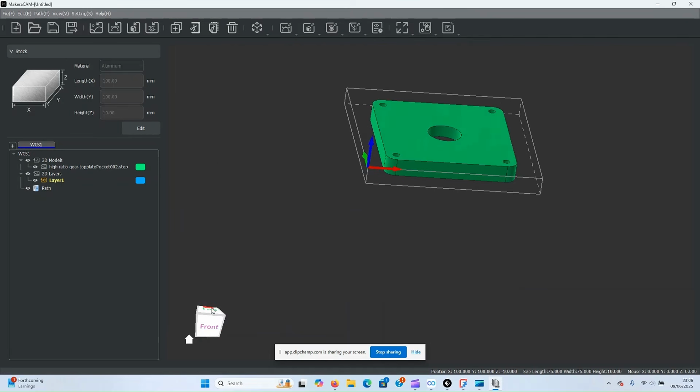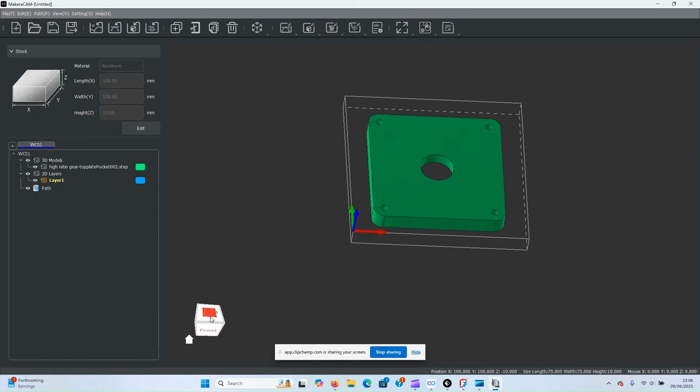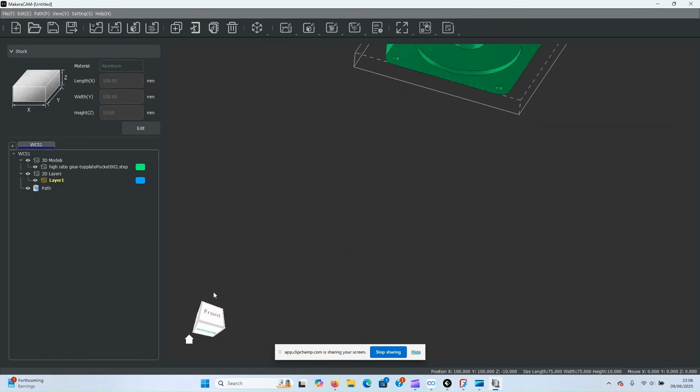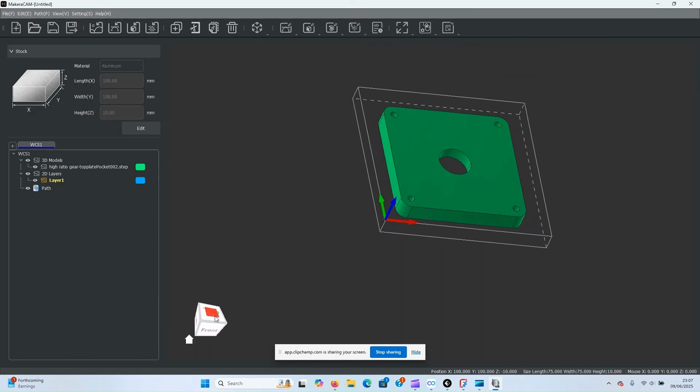When we scroll around that, we can see there's a top plate that we actually made in the video when we did FreeCAD. And if we swing that up, we can see that it's the wrong way around. Either I'm going to have to change the origin, which I can do by clicking on a point in the corner, or I need to rotate that whole thing. So if we click on that, and we do adjust object, you can see we've got transform and then we've got rotate.